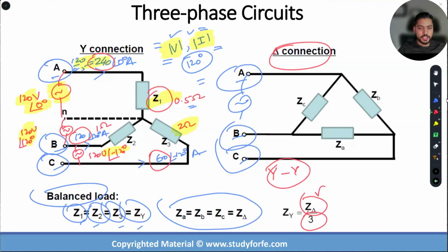Simply take each and every one of those delta connected loads, and this is assuming that they're balanced, by the way. In the PE Power Reference Handbook, we also entertain the situation, maybe it is on the next slide, when the system is unbalanced, when ZA is not equal to ZB is not equal to ZC. Even then we have a formula that is going to allow us to calculate for each of the phases the equivalent Y impedance.